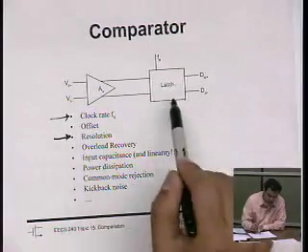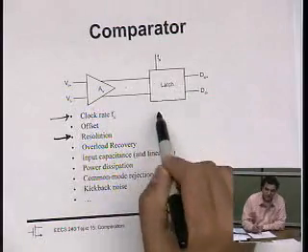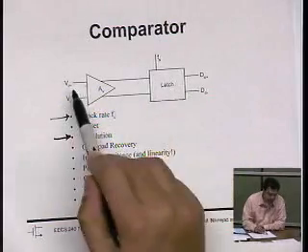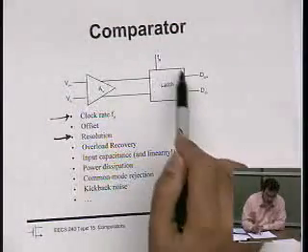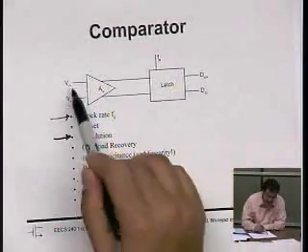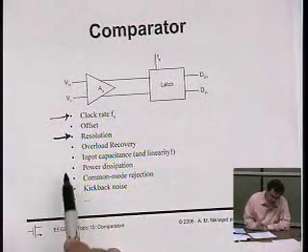And the nice thing about this two-stage design here is that if my latch has a lot of offset, input referred, it gets divided by the gain of this stage. So this is a nice way also to take a latch with a large offset voltage and input refer it. Some other issues which are more subtle.